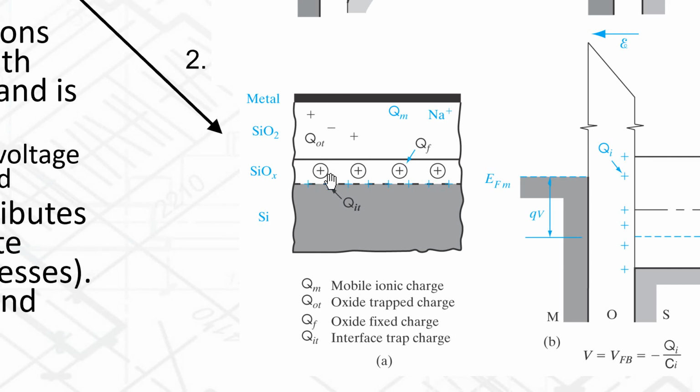And whenever you have positive charges in the gate oxide, that alters your electric fields. Because as you know, wherever you have positive charges, you end up having electric fields going away from the positive charge. And so that also alters your electrostatic potentials. Just so you see the sequence of events, let's say you had an unclean process, you were using tap water to rinse your semiconductors.